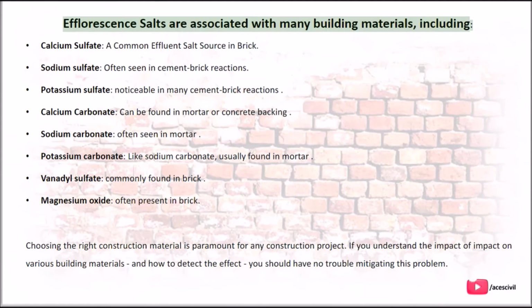Efflorescence salts are associated with many building materials, including calcium sulfate, a common efflorescence salt source in brick. Sodium sulfate, often seen in cement brick reactions. Potassium sulfate, noticeable in many cement brick reactions.